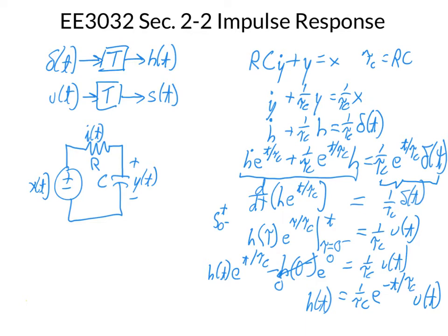So what this says is you have a voltage source. It's an impulse. It is very high for a very short amount of time. So maybe it's 100 volts for 1/100th of a second, so it has area 1, an area of 1 volt-second. And this impulse is the limit as that impulse gets shorter and shorter, but then the voltage has to go higher and higher to give us this input of 1 volt-second, which is the area under the delta.